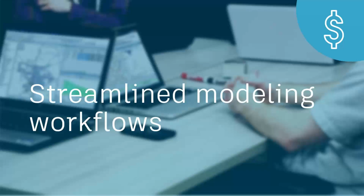But the thing that I'll keep emphasizing is that there's constantly going to be a need for calibrating your hydraulic model. And so the first part of this presentation was pertaining to leveraging the GIS to calibrate your hydraulic model. And then this second part is going to focus on how you can use that calibrated hydraulic model to perform modeling scenarios.